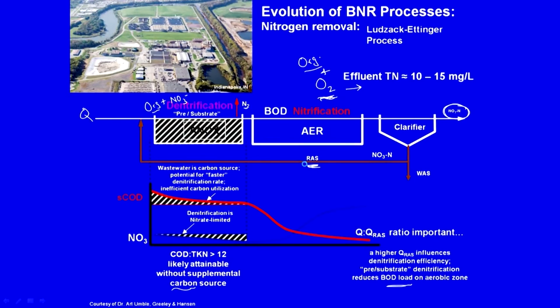For example, earlier we saw that here we do not have a lot of nitrate, right, and if I can get more nitrate here, then obviously I can improve the kinetics in this part of the system, but I cannot increase the return activated sludge to whatever level I want though, right. It is going to depend upon the mass balance. The RAS, return activated sludge, is going to depend upon the mass balance, and only then will I know how much I can pump.